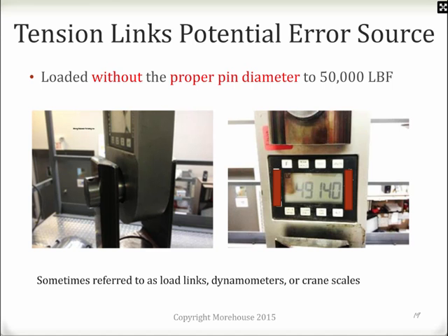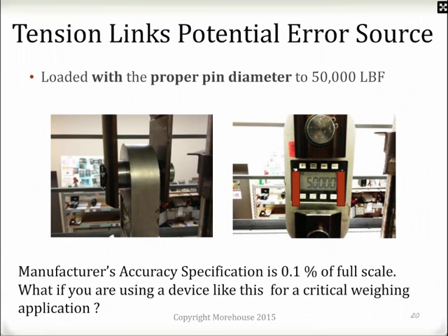If we look at the picture on the left, I call this slide loaded without the proper pin diameter. If you can see, there's still a lot of space in this instrument. So when we apply a force of 50,000 pounds to this instrument, we know it's not the proper adapter, but somebody else could just throw a pin in there and load it. The output here on this particular instrument was 49,140 pounds.